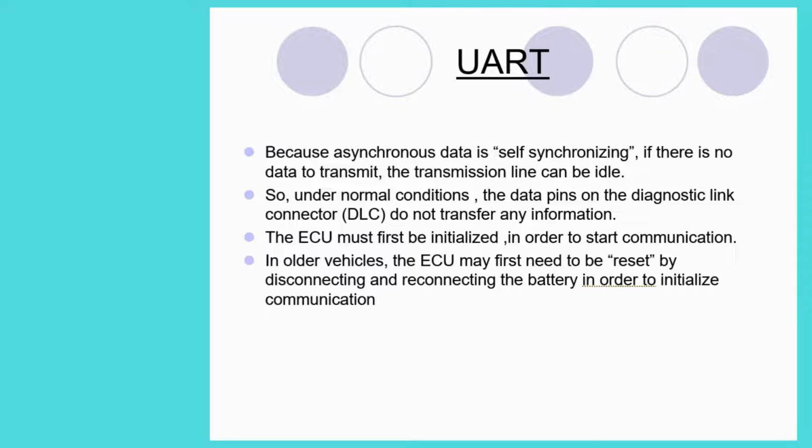Because asynchronous data is self-synchronizing, if there's no data to transmit, the transmission line can be idle. So, under normal conditions, the data pins on the diagnostic link connector do not transfer any information. The ECU must first be initialized in order to start communication.